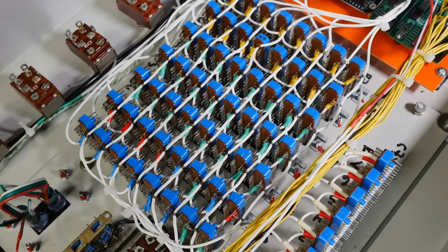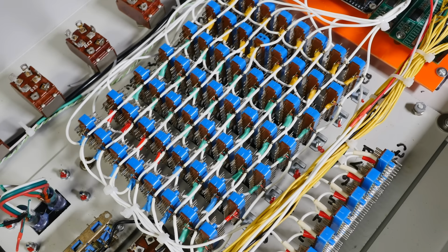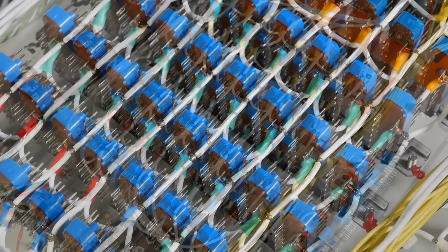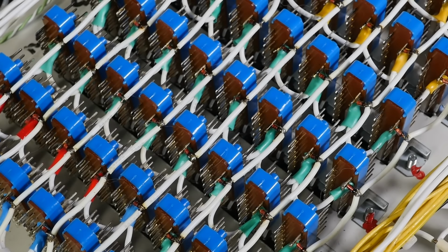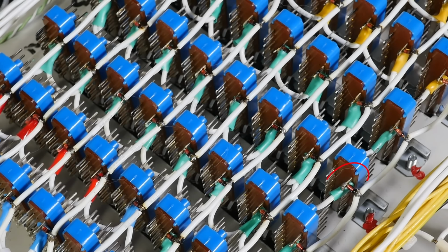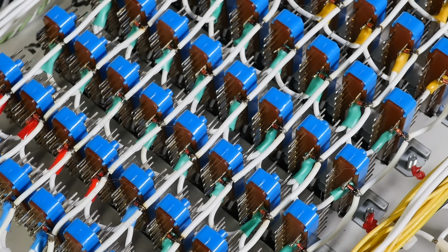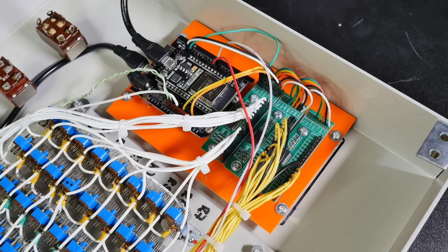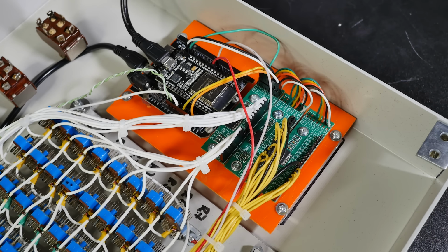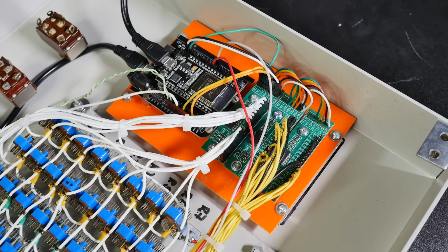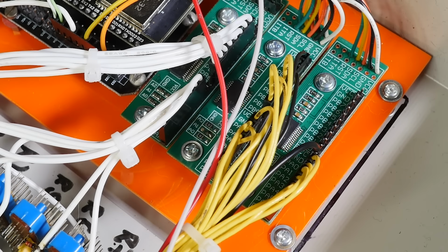The keyboard switches are matrices, so there are those lines for columns I showed before, and also I added lines for rows. The difference is that each switch in the row lines is connected through a diode, in a similar way to how it was done in the original keyboards. That's actually very important, because when buttons change, for a moment the matrix can produce some false signals. So all this wire mesh eventually reaches the GPIO expanders, and some pins here are used for rows and some for columns. But as you can see, there are some free pins.